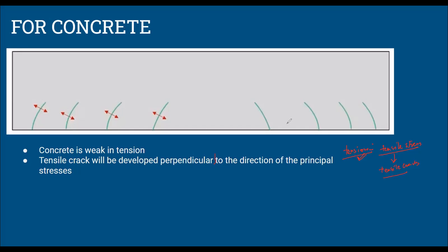तो basically what I mean, because it is in the tension zone, ठीक है, अगर ये न्यूट्रल एक्सिस है आप लोग का, if this is the neutral axis I am talking about, so this is the tension zone. तो टेंशन जोन में क्या होगा, टेंसाइल क्रैक डेवलप होगा. ठीक है, टेंसाइल क्रैक हो जाएगा ऐसे, और ये टेंसाइल क्रैक कहाँ होगा, this tensile stress will develop perpendicular to the direction of the principal stress. इस डायरेक्शन में आप लोग का क्रैक आना शुरू होगा. Now the direction of principal stresses you can find out from the trajectory. ठीक है, that is why that part was important.